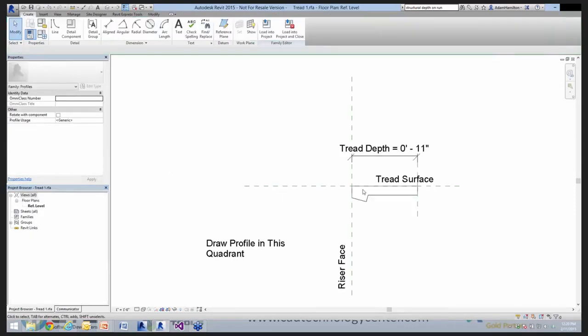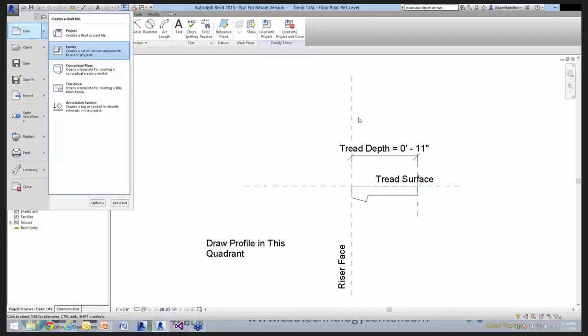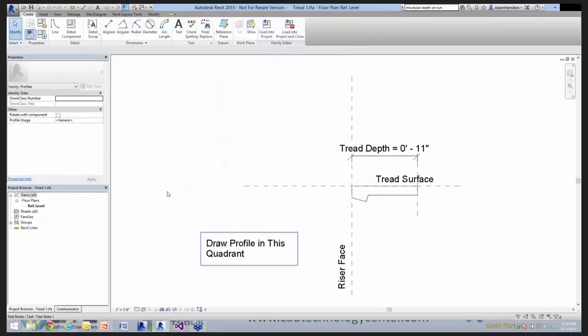Now, one thing, whether you're creating a tread or creating a nosing, the way profiles are read, because as you saw there's quite a bit of profile templates, I believe there's a good 5 or 6 of them here, the way they only show up in one dialog box or another is based on this profile usage parameter, and it's always good to make sure that that is set.